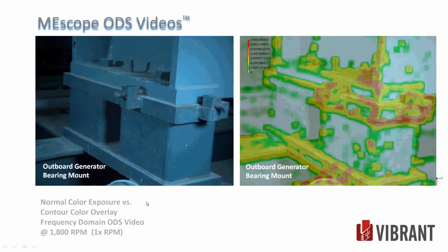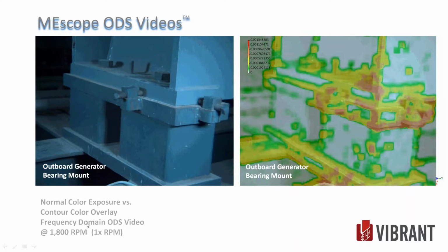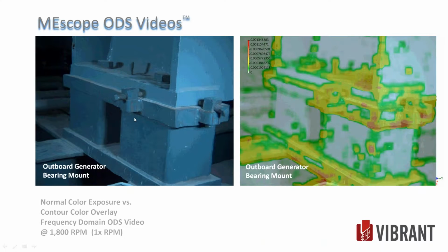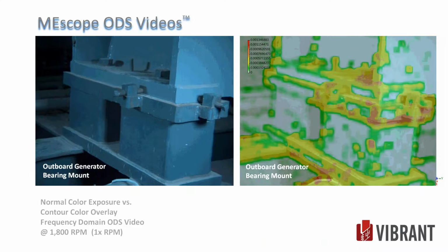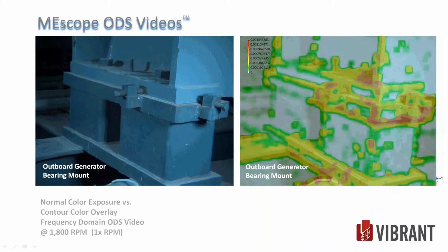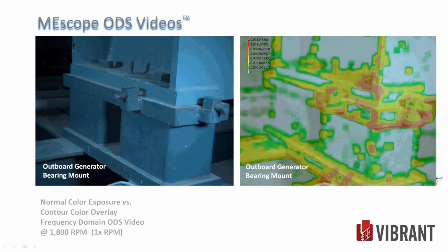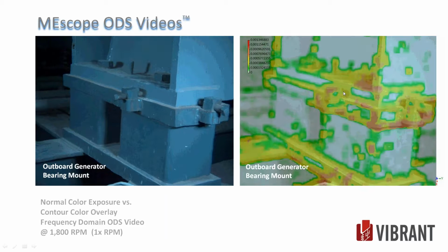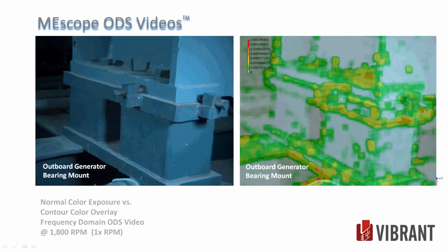One thing we did notice as we're running, right where I was standing to take this picture is the corner of the deck. And there's an expansion joint all the way around the slab. This framework was grouted in on top of that, but the corner I was standing at, the vibration level was almost as high there as it was on the bearing housing. So a little thought in my head, there's some kind of foundation issue going on.